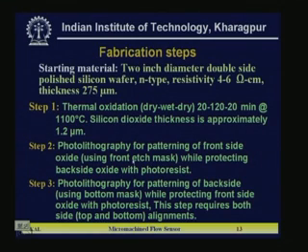Basically, the front side patterning means defining the total area of the sensor. In the rest of the portion you remove the silicon dioxide, so that when you etch from the backside, the top side boundary layers will also etch. Then, at the end of the process, you can easily break the sensor devices from the wafer.